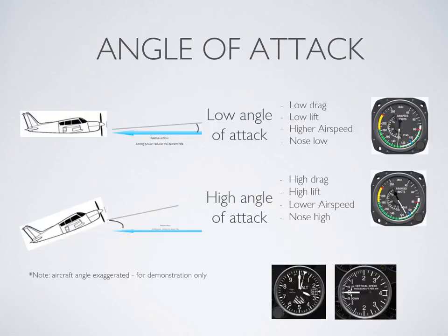What you're going to notice is that as we reduce the power, we're going to need to increase the airplane's angle of attack to get more lift at a cost of more drag. As we pass through the power setting that gives us maximum range, you're going to notice that we can continue to reduce power and not lose altitude. We are trading that extra lift out of the wing at a cost of more induced drag. And we're going to keep on doing this until we find the amount of drag produced by the wing starts to overcome the additional lift produced by that airspeed and power setting.